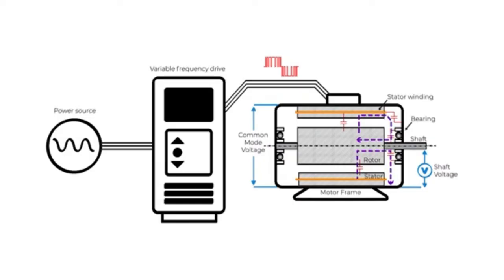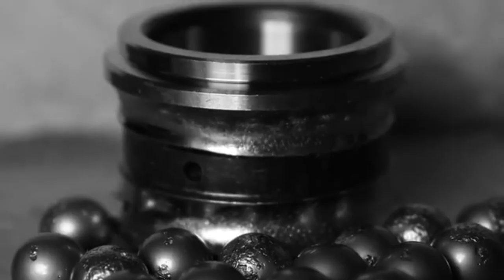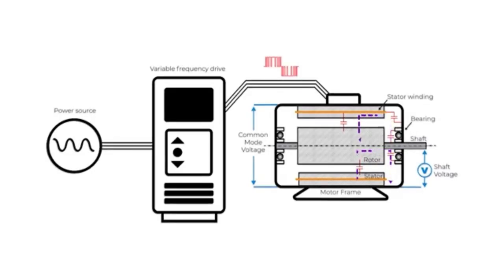When this charge gets high enough, it breaks the dielectric insulation and is discharged through the insulation of the bearing. The capacitive discharge current can cause fretting of the bearing and raceways and produces temperatures high enough to melt the bearing steel and cause pitting.